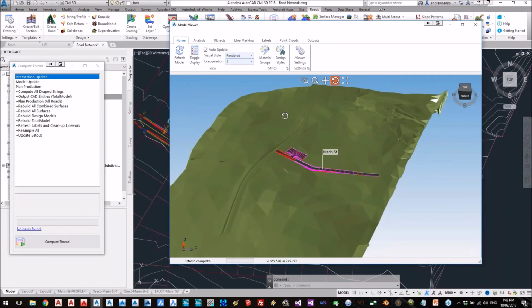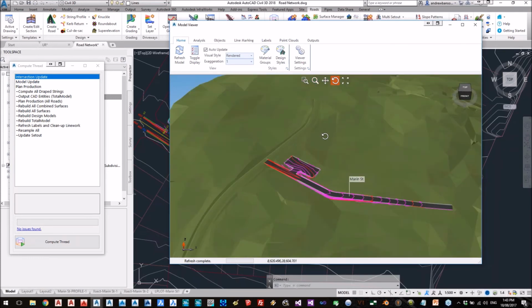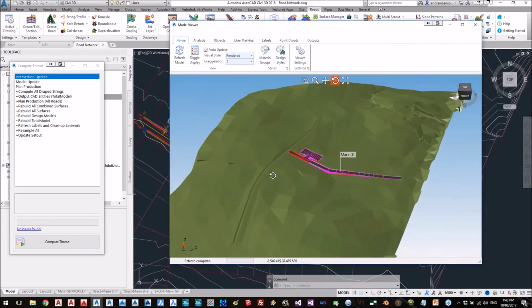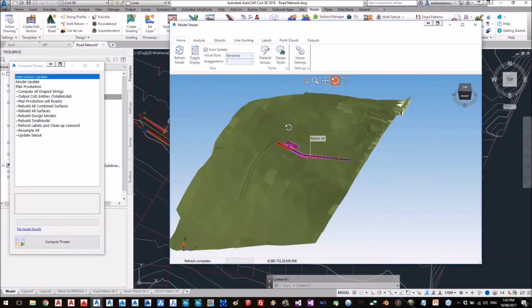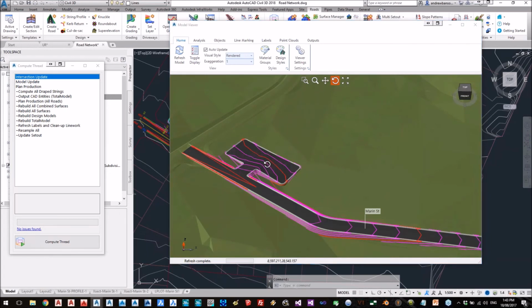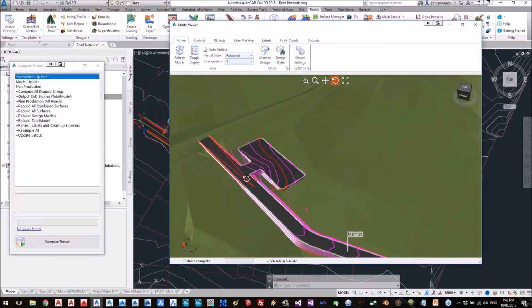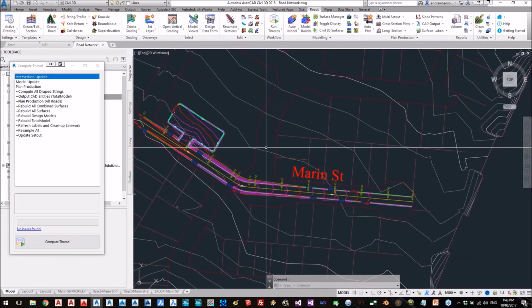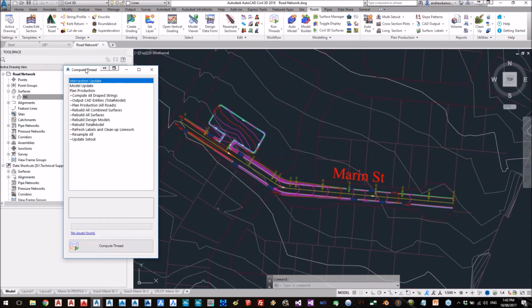The other thing worth noting in Model Viewer is we never really did a good job of boundaries. So if you had added boundaries to your natural surface or whatever, we'd still sort of triangulate across. We never really took notice of the boundaries. Now we do. So if I was to add boundaries to my base surface here, Model Viewer will now honour those boundaries. So just wanted to chuck a couple of those things in. As I said, in the next few weeks we do plan to release this version, and unless we encounter any setbacks or whatever, it should be out quite soon.